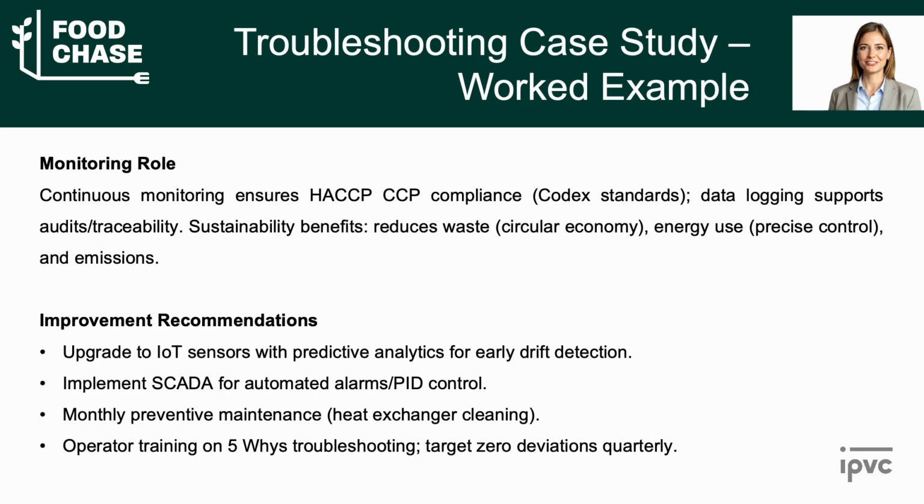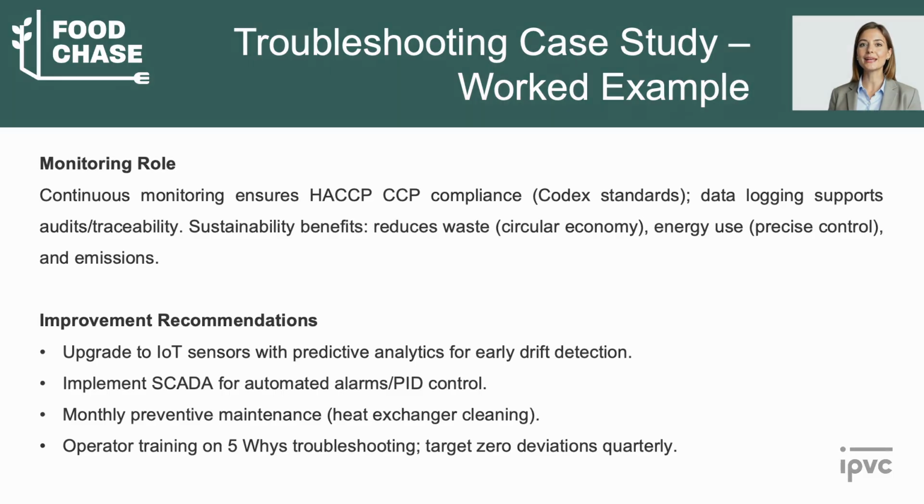Improvement recommendations: upgrade to IoT sensors with predictive analytics for early drift detection. Implement SCADA for automated alarms, PID control. Monthly preventive maintenance, heat exchanger cleaning. Operator training on 5 whys troubleshooting. Target 0 deviations quarterly.